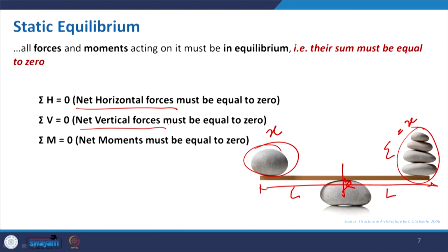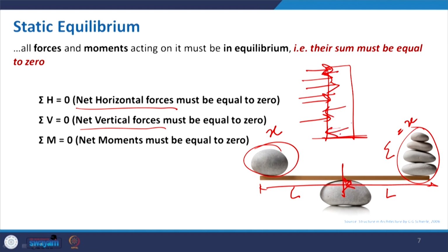Now, what about the horizontal force? Suppose you have a building and there is some horizontal pressure on it, and along with that there will be a reaction from the structural element. So, they should balance each other. It may be in a linear form or with the help of a truss or structural bracing. Depending on the height, requirement, size and scale, we determine different structural components which will balance this out, and the net result is that the horizontal force summation is 0.